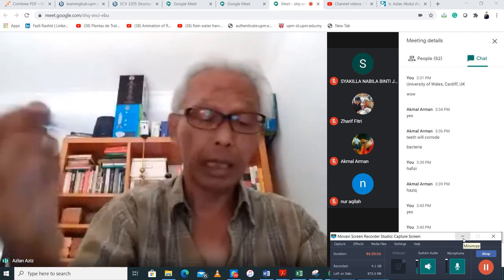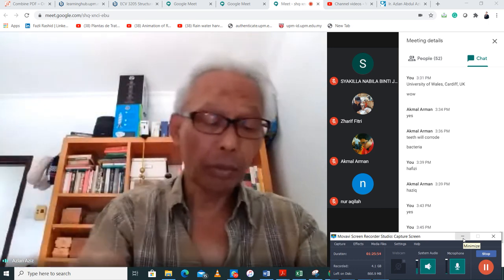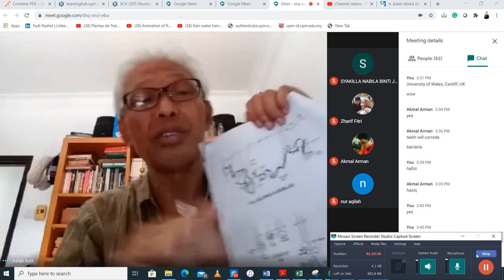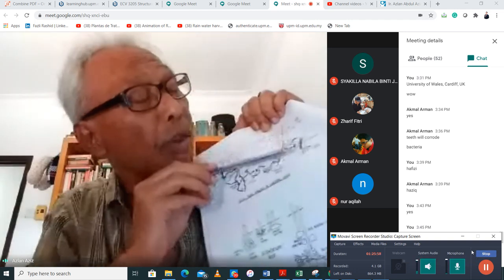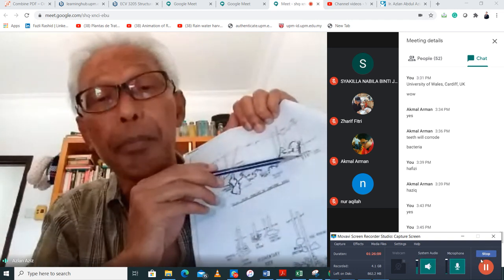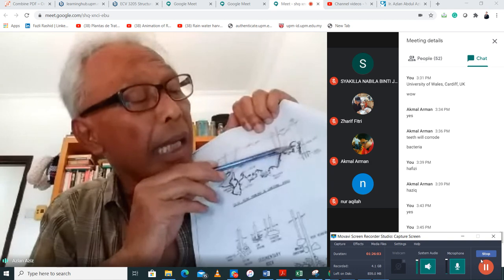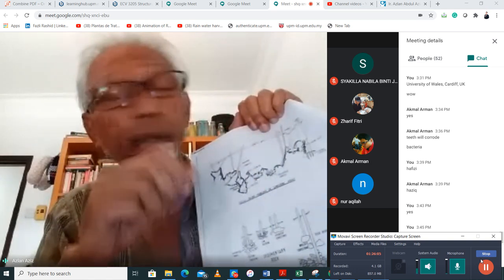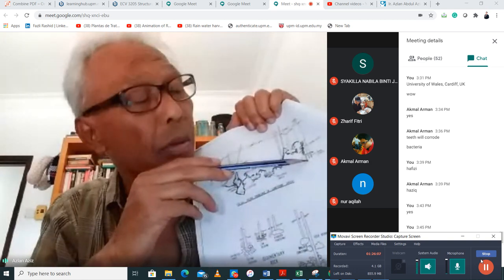And then you have that sinkhole. So the solution is this one here. What you do is that you put some small diameter piles, which we call micro piles, and then you bond it. You drill a hole in the solid limestone rock, all right?